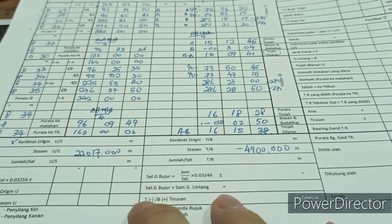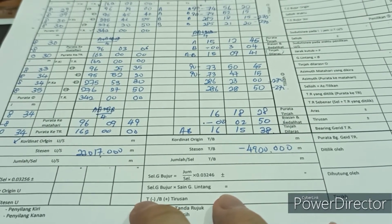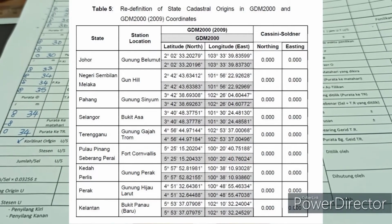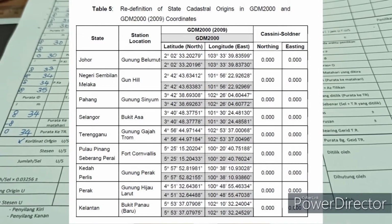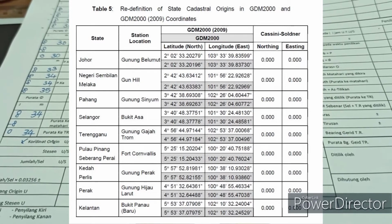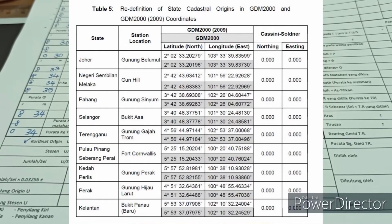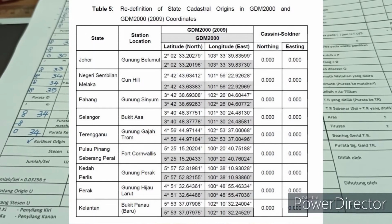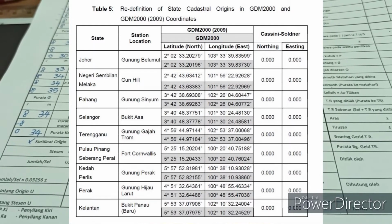So I will put a diagram of the coordinate in the video. In the diagram, we can see the Cassini origin for the easting and northing for Pahang state is 0, 0. And you can see the latitude value for Pahang state is 03 degrees, 42 minutes and 39 seconds.